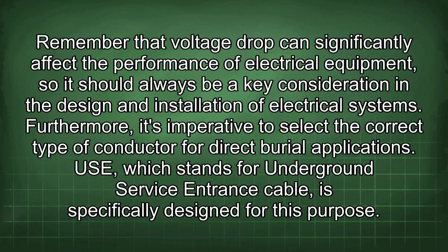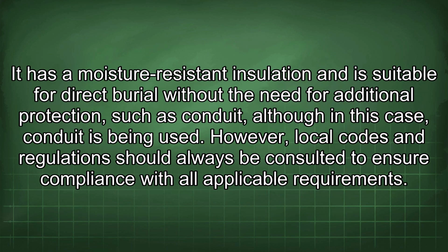Furthermore, it's imperative to select the correct type of conductor for direct burial applications. USE, which stands for Underground Service Entrance Cable, is specifically designed for this purpose. It has a moisture-resistant insulation and is suitable for direct burial without the need for additional protection such as conduit, although in this case, conduit is being used. However, local codes and regulations should always be consulted to ensure compliance with all applicable requirements.